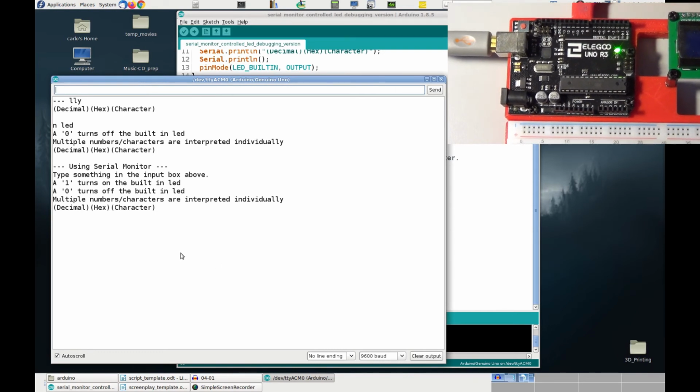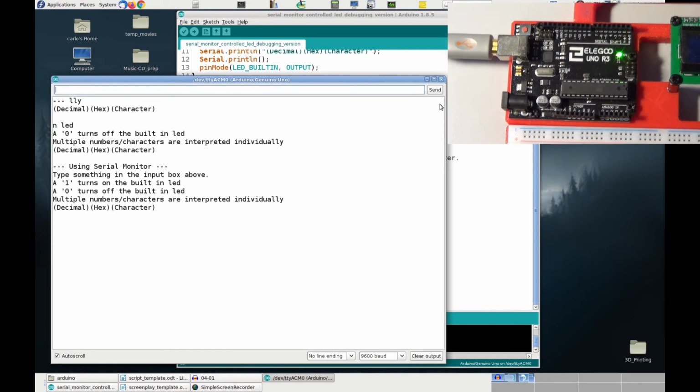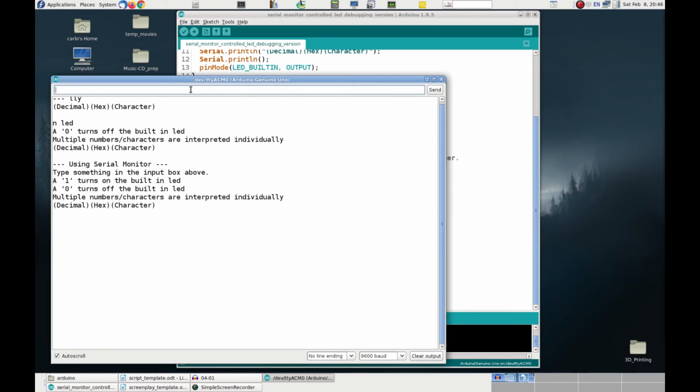This is how usually a program is executed on Arduino. We don't put many printouts in there. First, because we do not need them once we run the program in normal conditions, because we are not going to look all the time at the serial monitor. And second, because those printouts take valuable space in the Arduino memory, thus limiting the size of the programs that we can write on it. So in the end, we only put those printouts that we really need, and once we are sure the program works fine, we can even remove them if we don't need them anymore.